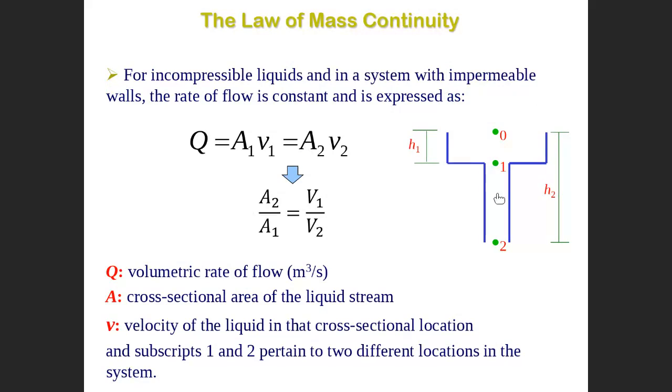Then we apply the flow rate here. We put the liquid here at a constant rate. Then this will definitely provide exactly the velocity needed at point 2 to avoid aspiration. In this way, you can satisfy the condition of avoiding aspiration and porosity in metal casting, or getting defects in metal casting.